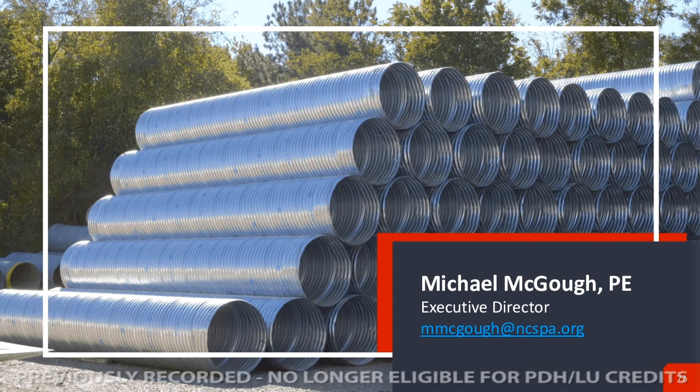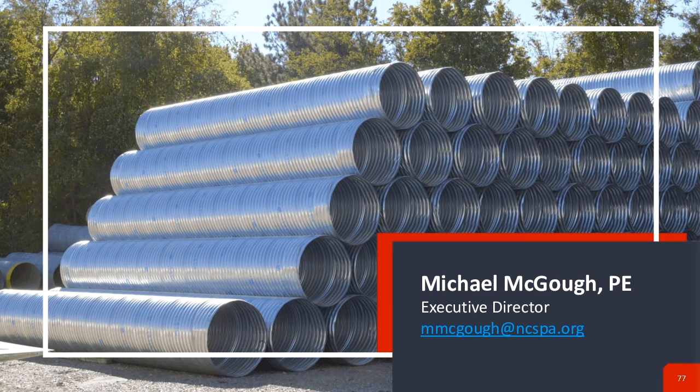Eric right here just asked about ventilation for confined space entry. Yes, you do have to have ventilation within the systems for confined space entry, and you do have to follow all the OSHA requirements in order to go in and maintain these things. Yep. And then Daryl's explained in the chat room that as long as these systems are below the frost line, then freezing is not an issue, right? Most of them are, or would be.